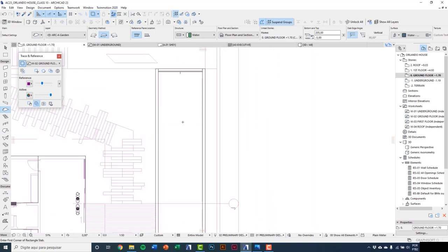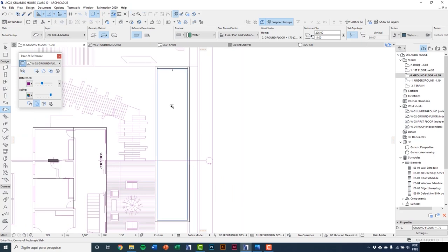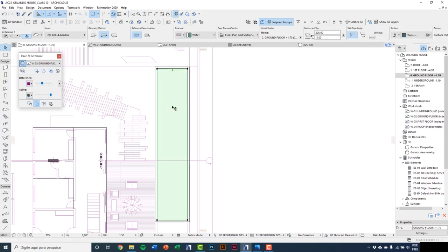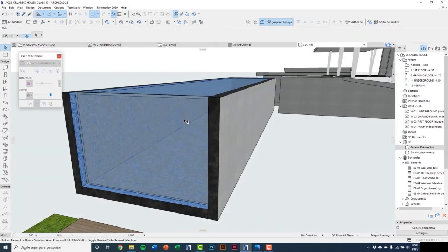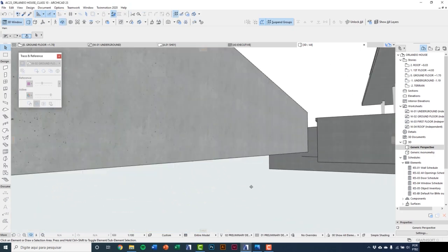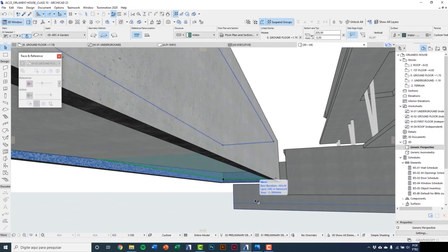To design, I can even use magic wand to fill, space bar and click. The water needs to be brought to front. So I choose pressing the tab. I can alternate between elements. Here appears slab to me. I click and bring to front. Looking on 3D, you see the water surpassing the pool bottom because it has a sloped structure.